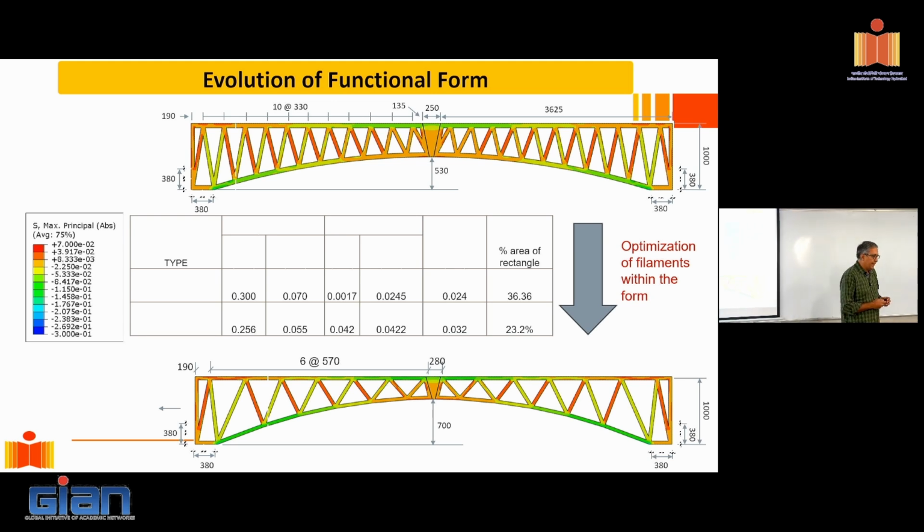Yeah. So the key element has to be a little up. Only then do you develop the restraint at the bottom. Otherwise, you won't develop that. If you look at it this way, right? Now, this is what we put as 250 millimeters, it is flexible, 250. And that will be adjusted on the site. So what we do is we hold up these two pieces, then do the closure pour, and then remove the support. So only then will the restraint come.